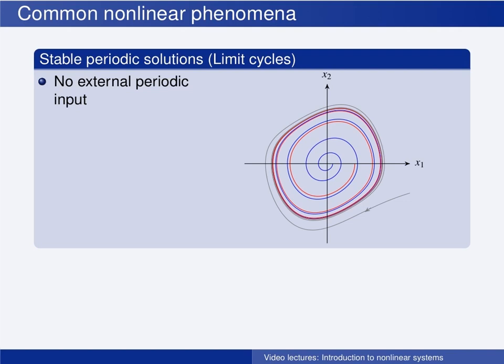Specifically, if the input to a system with transfer function H(s) is a sinusoid u with some amplitude U and some frequency omega, then the stationary system response y_s to this input is a sinusoid that has the input amplitude U scaled by the magnitude of H evaluated at s = j omega, where omega is the frequency of the input signal.